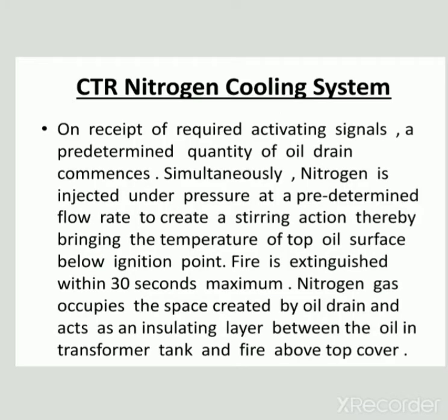Next one is the CTR nitrogen cooling system. What is the purpose of this cooling system? On receipt of the required activating signals, a predetermined quantity of oil drain commences. Simultaneously, nitrogen is injected under pressure at a predetermined flow rate to create a stirring action, thereby bringing the temperature of the top oil surface below the ignition point. Fire is extinguished within 30 seconds maximum.